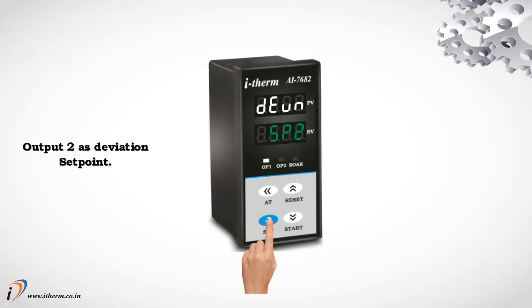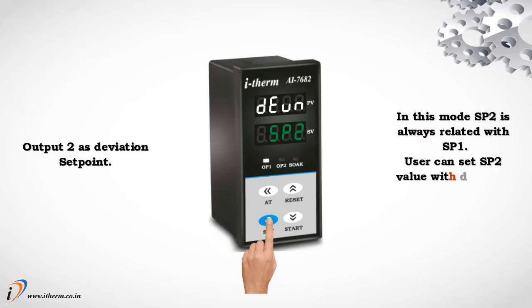Output 2 as deviation setpoint. In this mode, Setpoint 2 is always related to Setpoint 1. User can set the Setpoint 2 value with a deviation of plus or minus 99 degrees Celsius with respect to Setpoint 1.